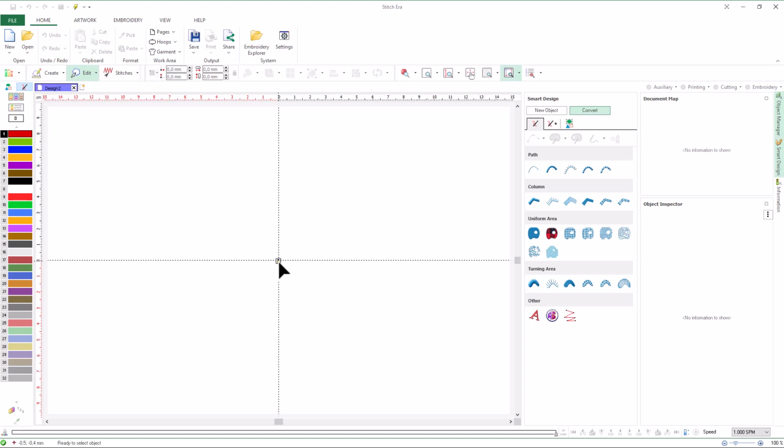We can do it manually, visually following their edges, or we can use auto trace to recognize the contours of the regions in an automated way. Although auto trace also works with vector images, it is much more useful with raster images. The tool works much better with images with well-defined edges and an acceptable resolution, at least about 200 dpi.